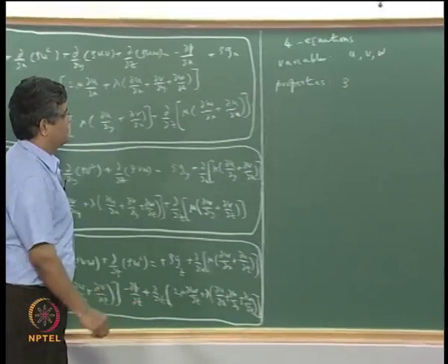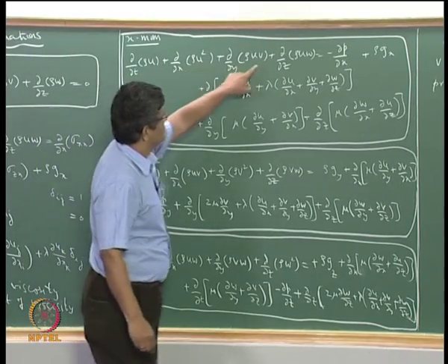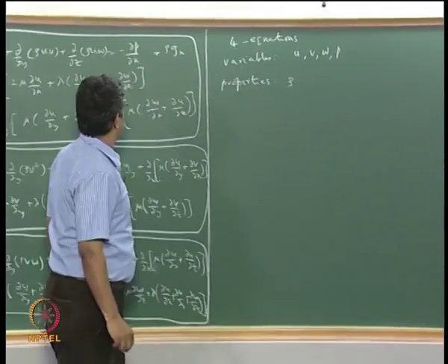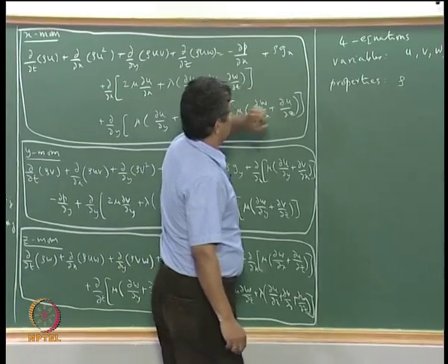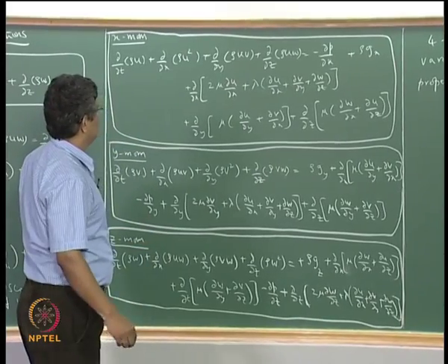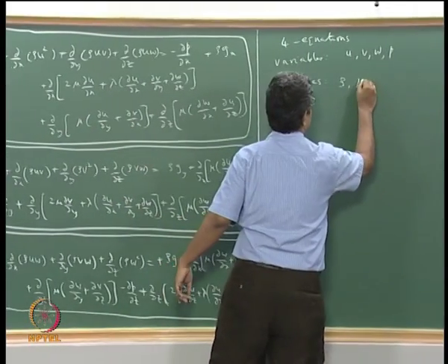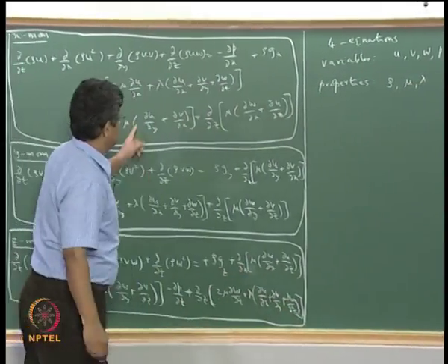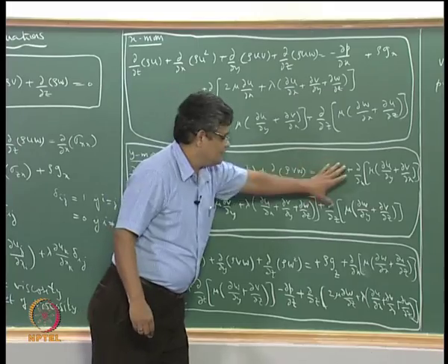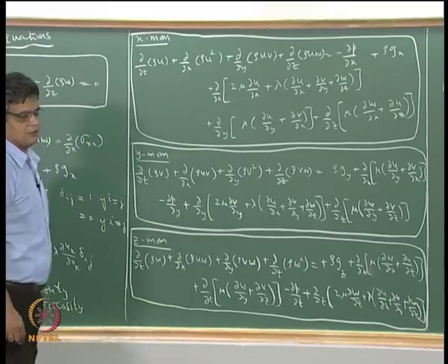We have rho, which is the density, and in the x momentum equation we already have rho u w here, and pressure is coming, which is a flow variable, and of course g is a gravitational vector. We expect it to be specified in terms of the orientation of the control volume. We have mu and lambda, otherwise everything else is given here. In the y momentum equation, no additional variables. In the z momentum equations, no additional variables.